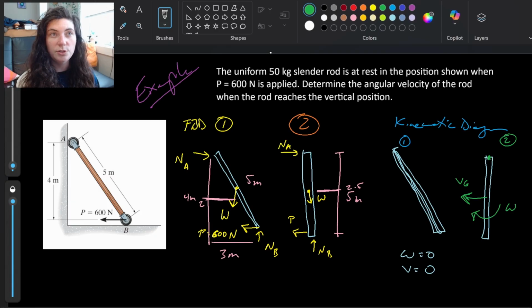And so using this A as a base point, we can say, all right, I have this R vector, R of G with respect to A, showing the kinematics of that. How does position relate to our angular velocity and our radius? How do these vectors work together? VG, omega, and R. So R is the thing that unites those VG and omega vectors.